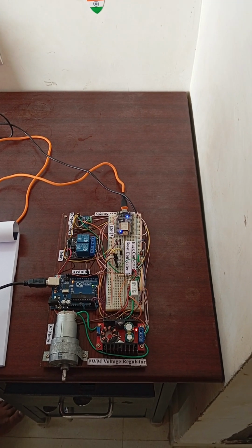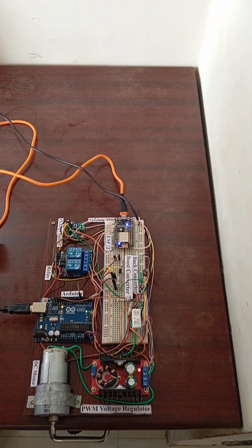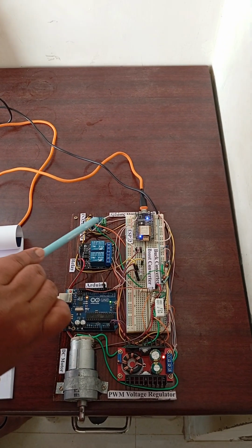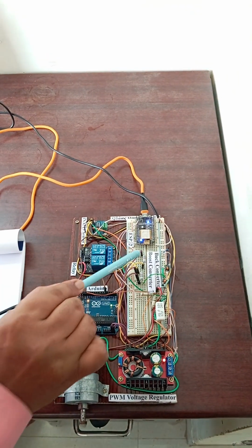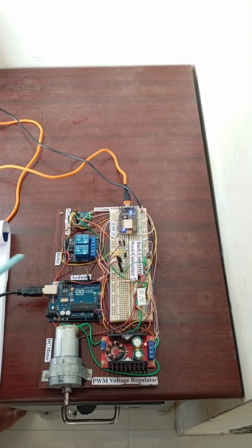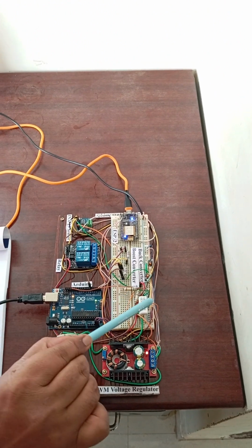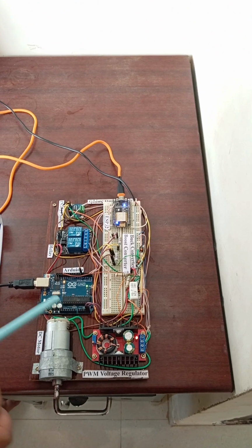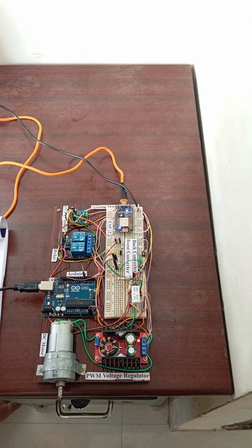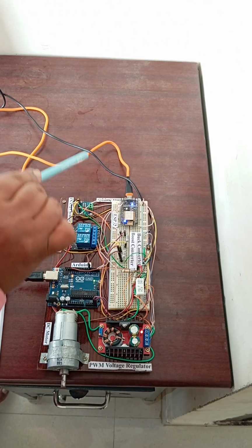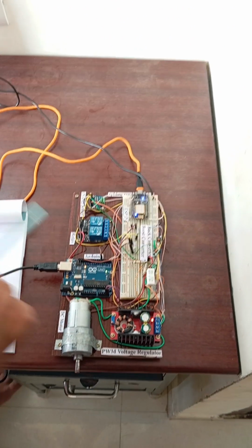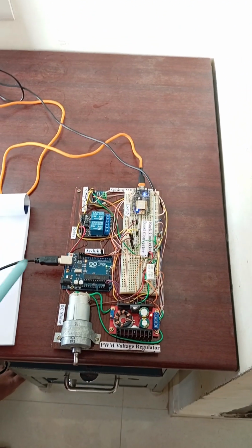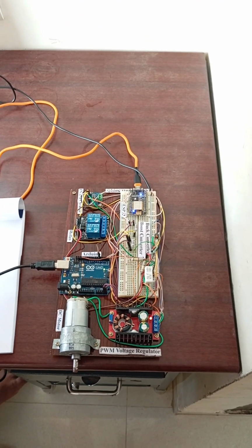So coming to this, this is used as a Wi-Fi module, and this is the current and voltage sensor, connected by using SCL and SDA connections with pull-up resistors, these are pull-up resistors of 4.7 K, and this is one more resistor of 0.1 ohms. Through this, the motor currents and voltages are sensed by these sensors, and these sensing values are sent to the Arduino. And by using the Wi-Fi communication module, we made use of the HTTP protocol for cloud transfer.